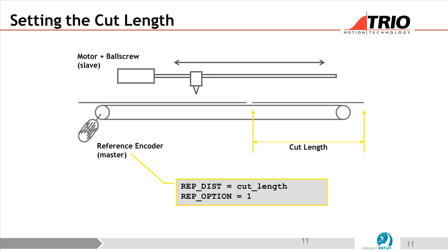We're looking at plain material here. It's not got any marks on, so we're not worried about synchronizing with anything on the material. We just want to cut it to exactly that length. These are the sorts of things we've been involved in. Take the metal strips in the ceiling: they want those to come out of a machine, being extruded or rolled out, and they just want to cut them to however many meters long. So you have a flying shear that does that. It just chomps them, and then they go into a container and off to the builder. All you want is to repeatedly produce 5 meter lengths or whatever, or 1 meter length. So all you want is a length in there.